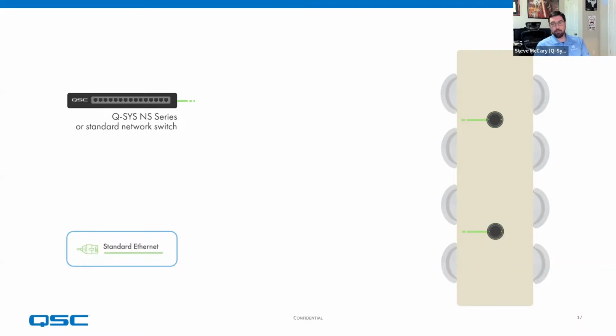So the Nmt1 microphone block, when you bring that in, and this is something that we'll dive deeper into when the mic is actually out, which I believe is going to be 9.7 now, we'll go into that in a little bit more detail, but the Nmt1 block actually has AEC built into it, so you don't run that through a separate AEC processor. The AEC processor is just for either Dante mics or analog mics or something like that.